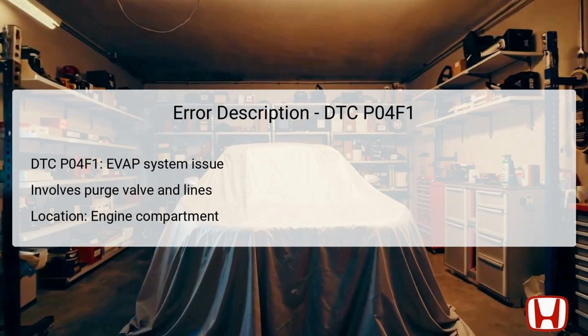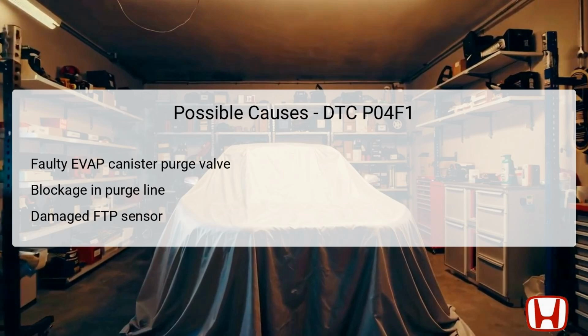If the flow is insufficient, it may cause the vehicle to fail emissions tests and may lead to engine performance issues like stalling or rough idling. Understanding the roles and locations of these components is fundamental to effectively diagnosing the issue associated with DTC P04F1. There are several possible causes for the DTC P04F1, each contributing to low purge flow in the EVAP system.